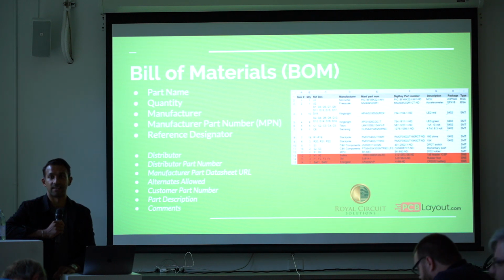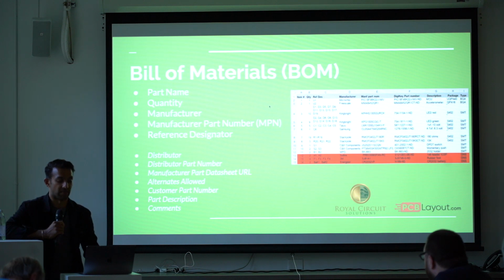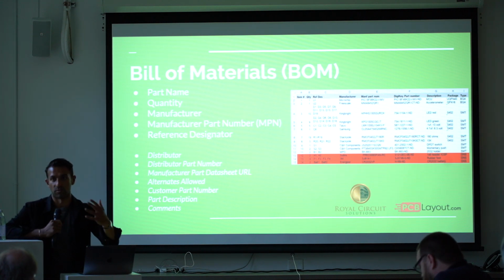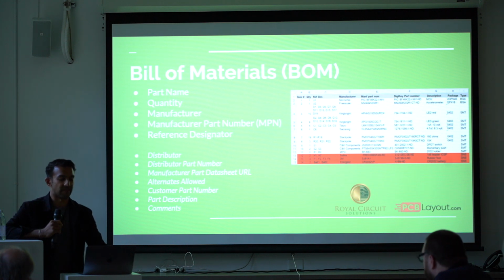What's the part name? Oh, literally the name of the part, like what is this part, matching with the silkscreen? Is it your capacitor, your inductor, just as a high level indicator of what's going on? And you need that, right? The MPN isn't enough, right? The MPN should be the unique identifier. Manufacturer plus MPN is unique. Yeah, I agree, that's fair. All right, you got me.